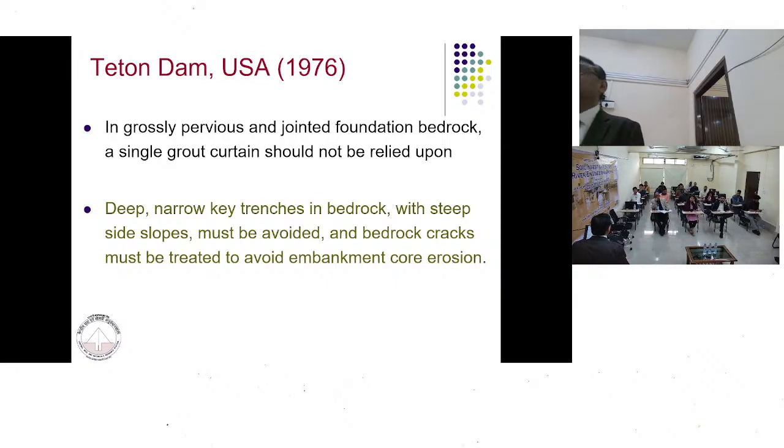How can the permeability test be wrong? Can you tell me? How can a permeability test be wrong? In one of the cases, we saw that the permeability test was wrong because the water meter was not functioning. Can you understand? The water meter which is used in the permeability test was non-functional. Water was being pumped through, but it was indicating very less flow.